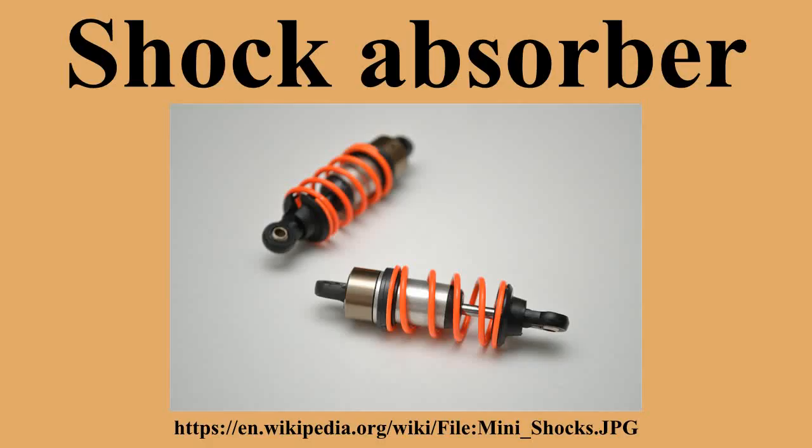Spring rates are chosen by the manufacturer based on the weight of the vehicle, loaded and unloaded. Some people use shocks to modify spring rates, but this is not the correct use. Along with hysteresis in the tire itself, they damp the energy stored in the motion of the unsprung weight up and down. Effective wheel bounce damping may require tuning shocks to an optimal resistance.